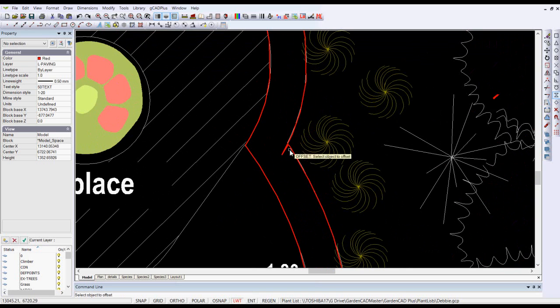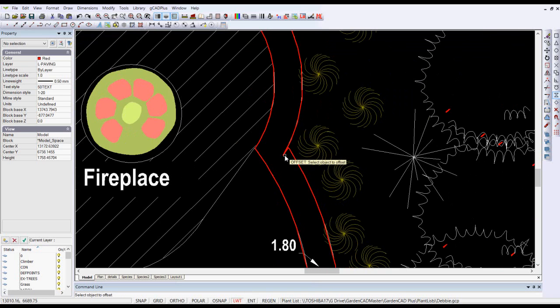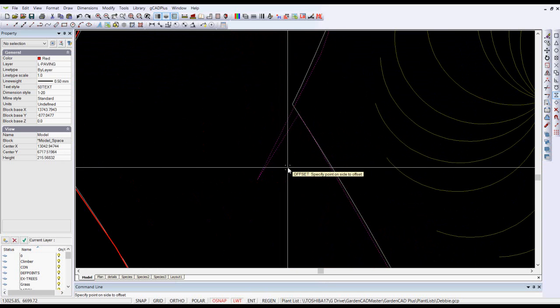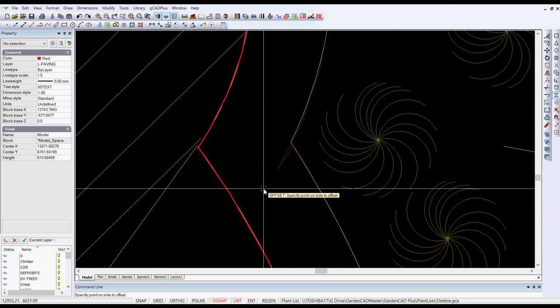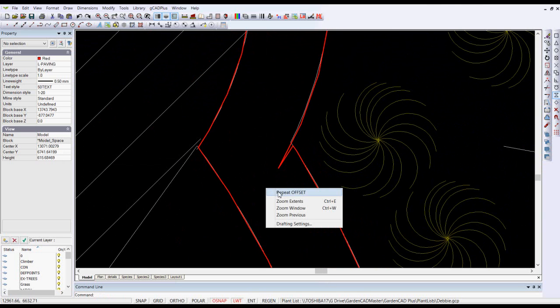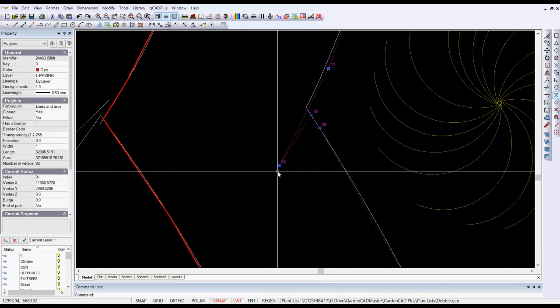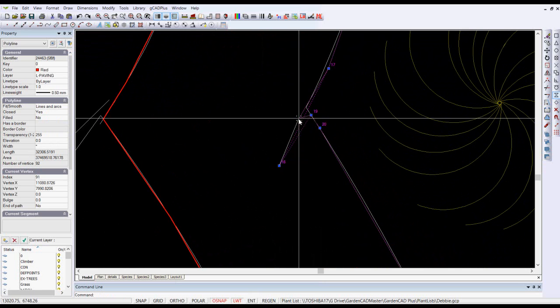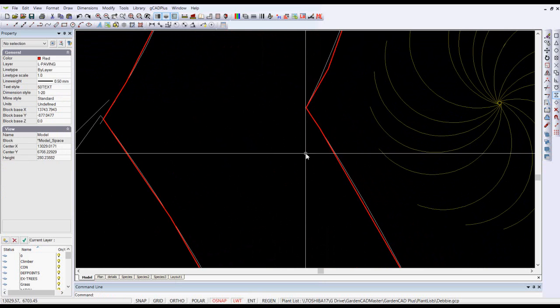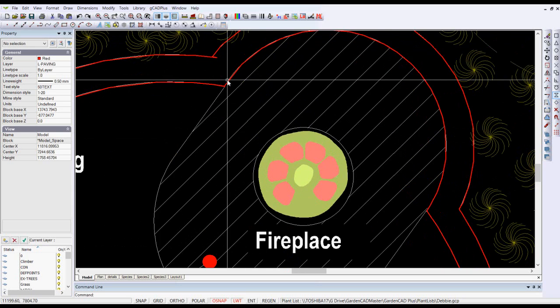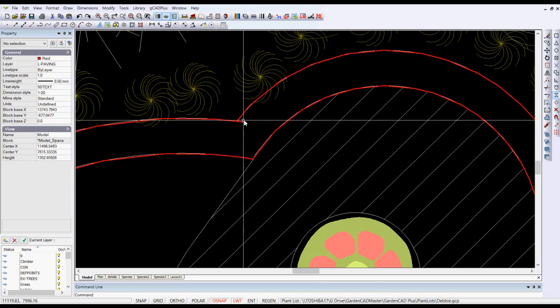You notice that we got an imperfect clip in here, but we should be able to edit that polyline when we cancel from there, pick the polyline and click that point there and bring it back to there, and that one looks okay. We may have another imperfection up here.